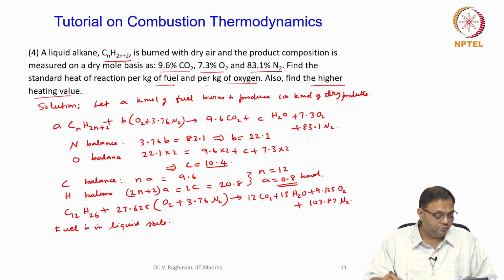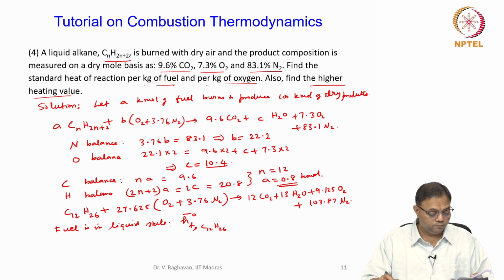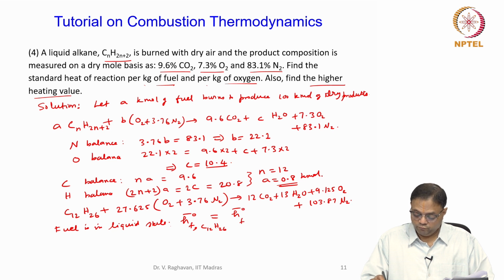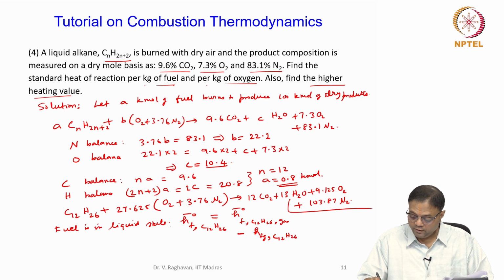So that means the enthalpy of formation of the liquid fuel C12H26 will be equal to the enthalpy of formation of the fuel in gas phase minus hfg of C12H26, that is the latent heat of vaporization.